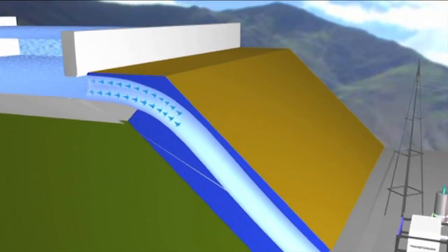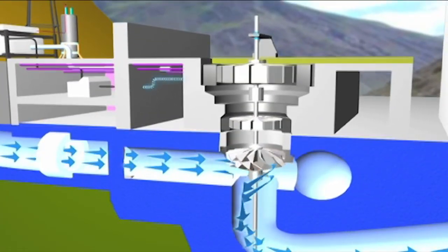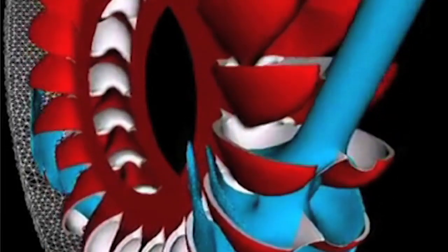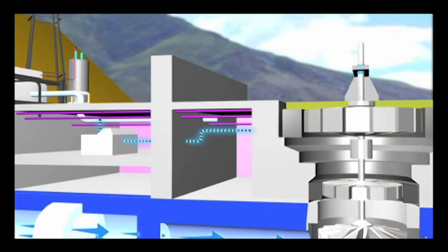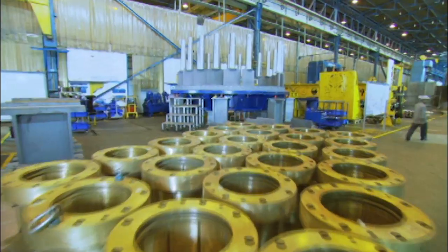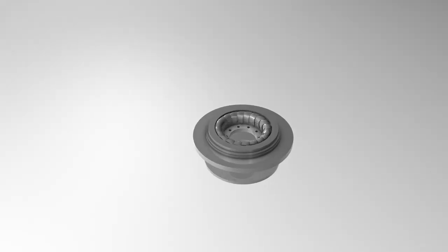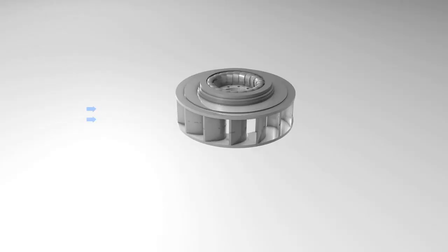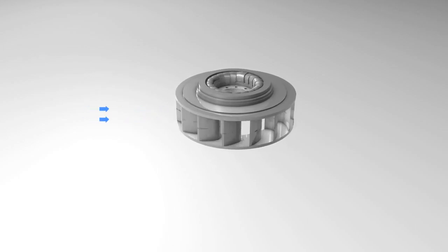Turbines. Turbines are used to extract energy from moving water for the production of hydroelectricity. They operate by forcing water past slanted blades, which spin the turbines. Turbines are mechanically attached to an electric generator, which generates electricity. Most common types of turbines used are Francis. The Francis turbine is a reaction turbine. Guide vanes direct the water tangentially to the runner, and this radial flow causes it to spin.